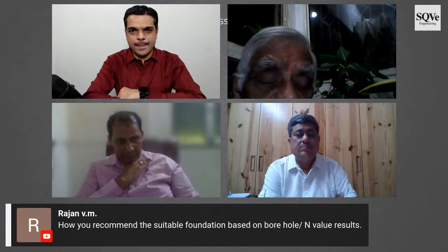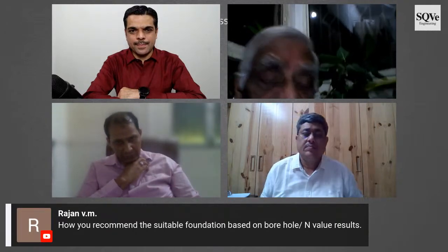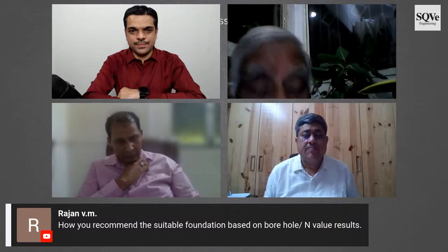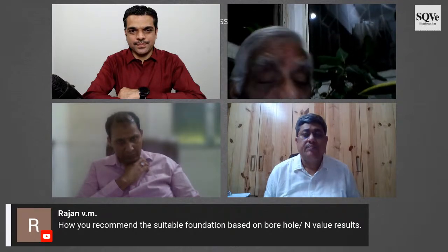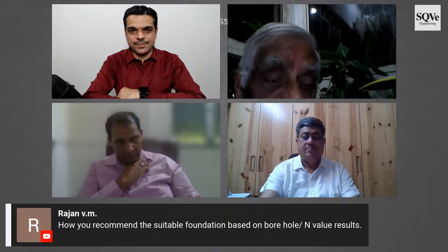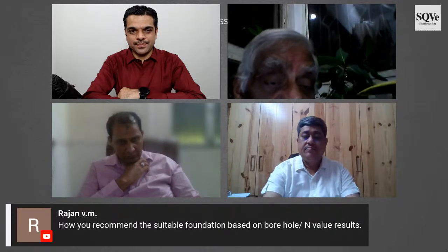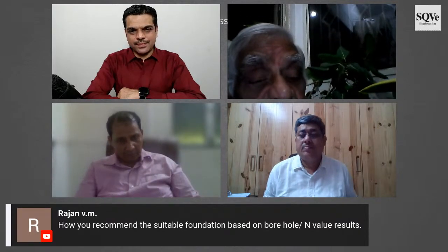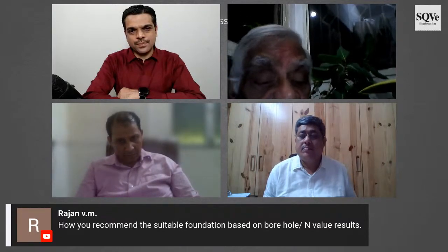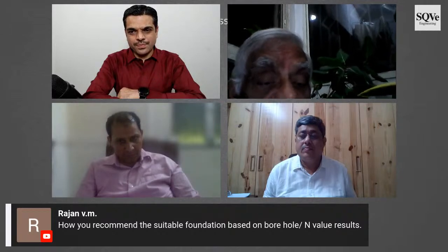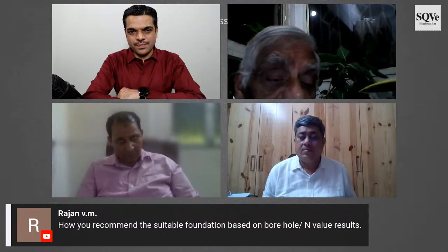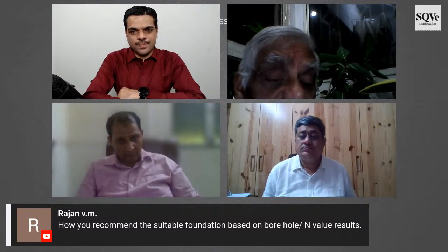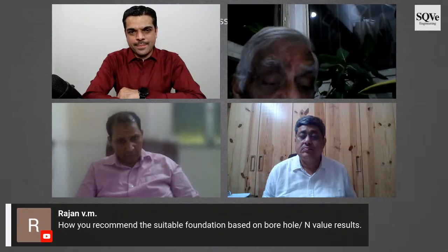I remember when I did the optimization study, because I'm basically a structural engineer. I'm interested in soil investigations and soil mechanics. I'm also interested in hydraulics. I love hydraulics as much as I love structures. So when we did the optimization study for a circulatory water system, we found that the auxiliary units were consuming very high power. So I decided to increase the diameter of the pipe from 2150 to 2650 so that the auxiliary power consumption comes down, and the cost was going up.